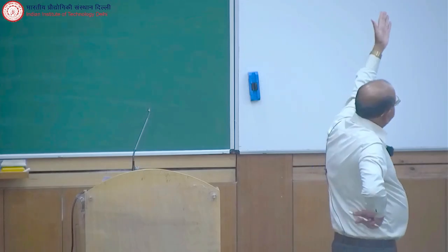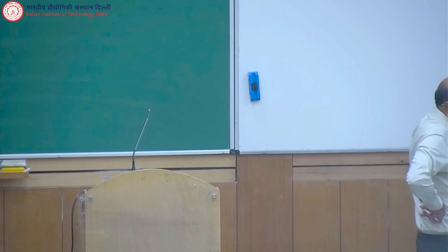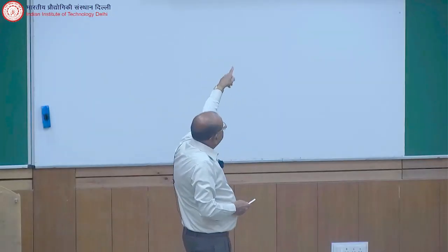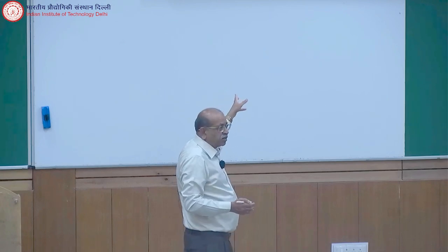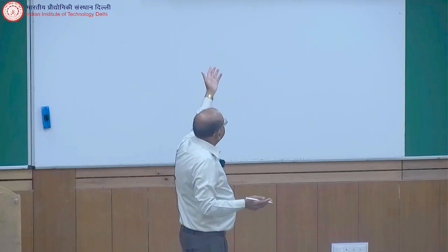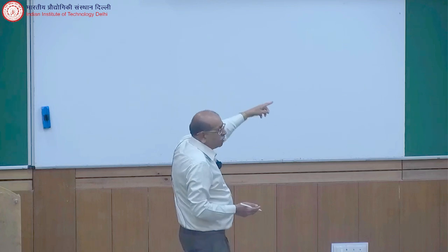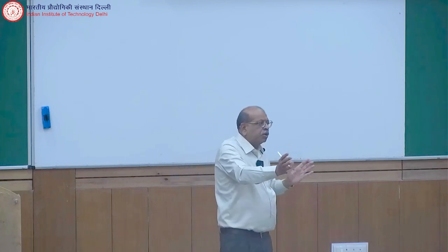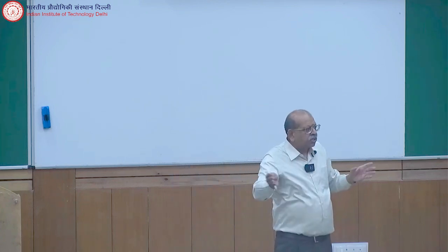So, as we said, if there are different streamlines, and the point I was trying to make is, if Bernoulli's constant for A and C are the same, then actually you could apply Bernoulli between A and D also. But notionally, you should always apply it on the same streamline.